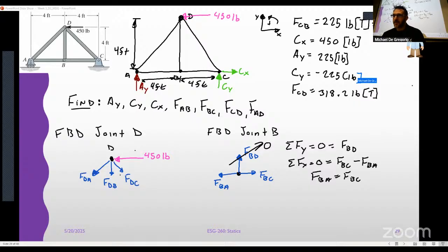Because it comes out positive. If I were to plug in 225 here, it's going to stay positive. Keep track of the things that we found. That's equal to 0 pounds. Okay. If you don't feel comfortable looking at a structure and saying that's a zero force member, the math will always back it out for you, right?